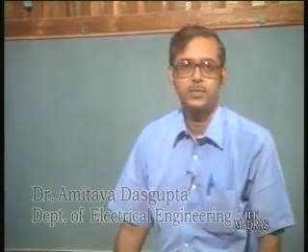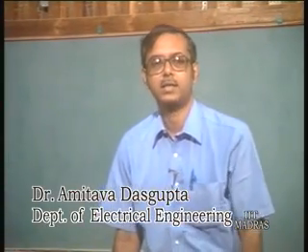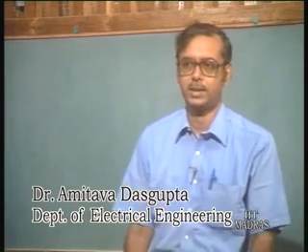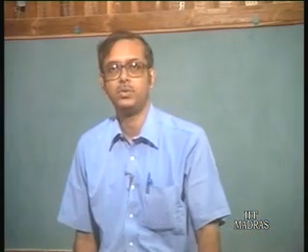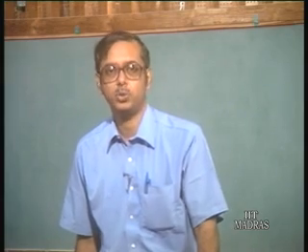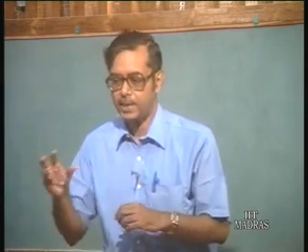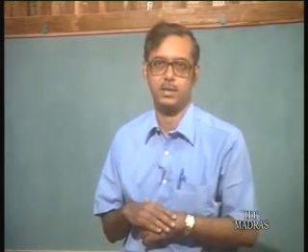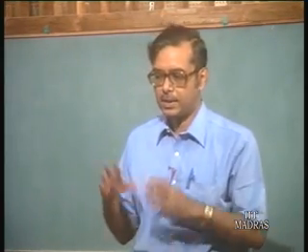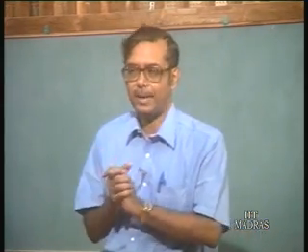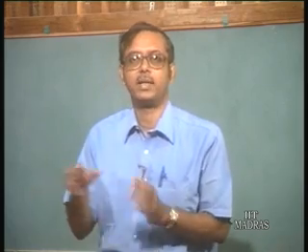In the last class we had started our discussion on MESFET based logic circuits, and we had discussed two logic families, that is the direct coupled FET logic and the super buffer FET logic, both of which use a combination of enhancement mode and depletion mode transistors. Now it is sometimes difficult to fabricate both enhancement mode and depletion mode transistors in the same wafer.